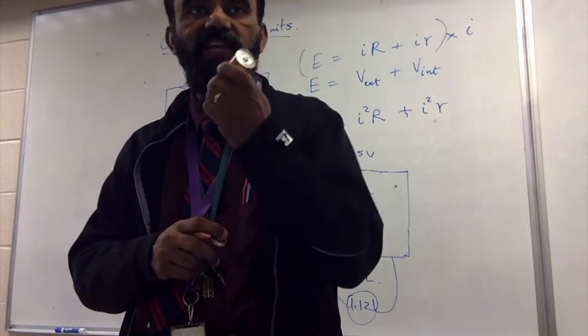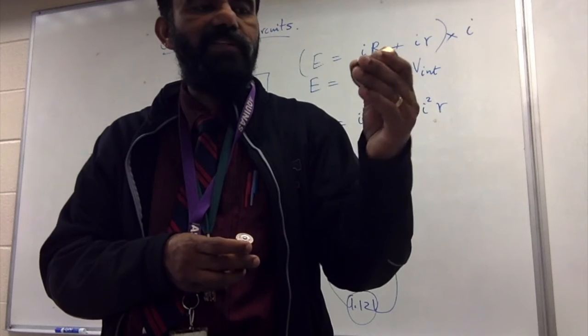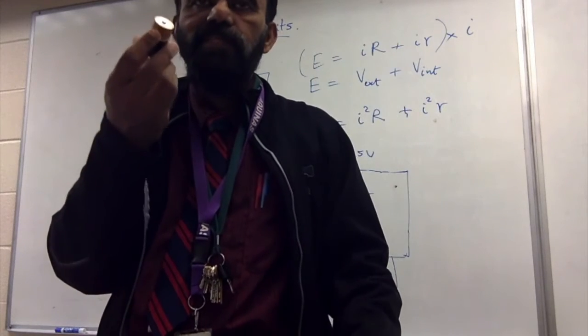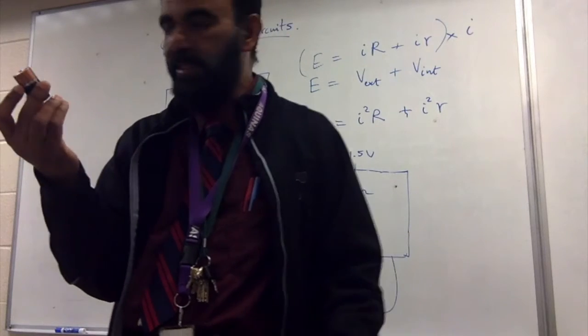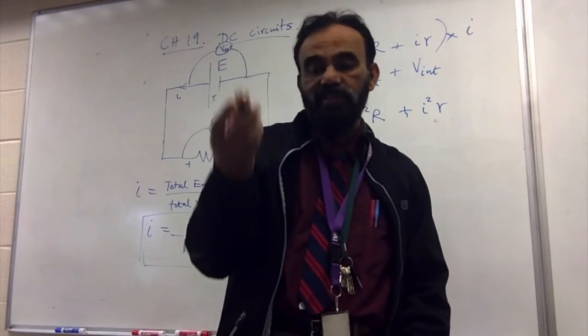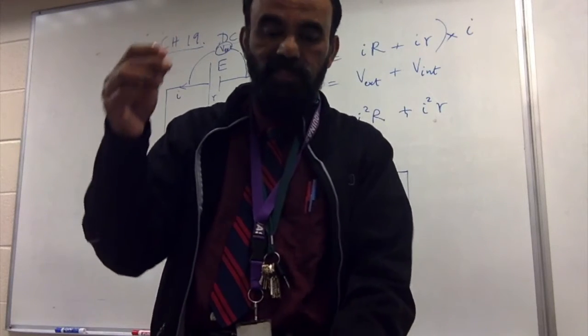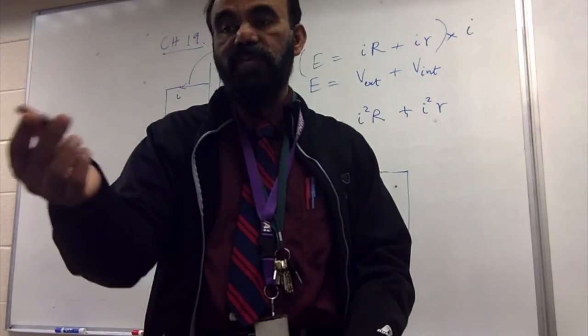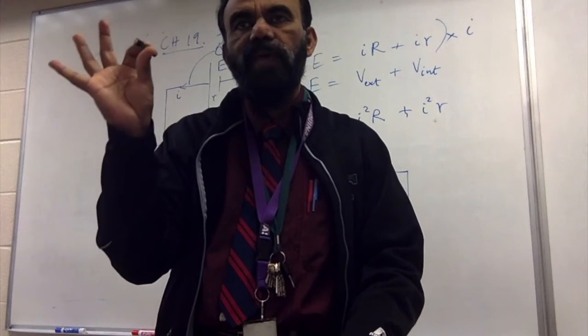So if you have a flashlight where 2 of this or 3 of this is used, I cannot just substitute that with this because this one, to begin with, has higher internal resistance, right? And the same way, this one has still higher. So using these in your calculator is okay, because the calculator requires only a small current.